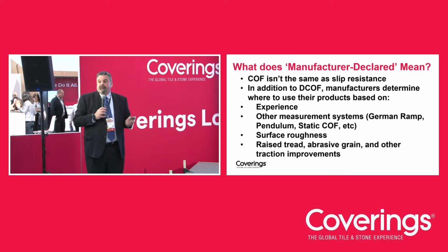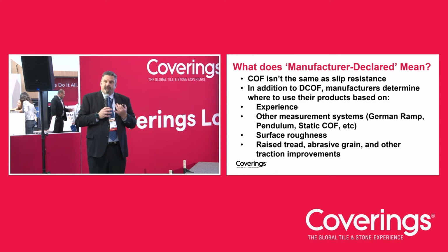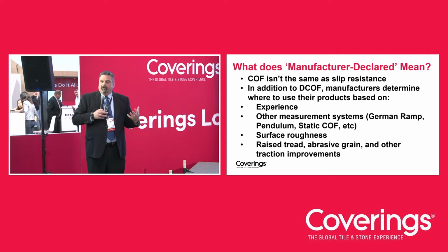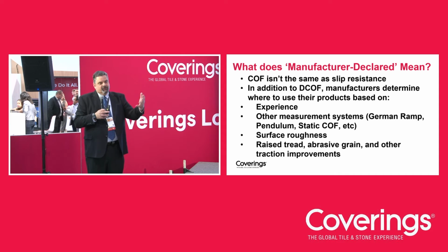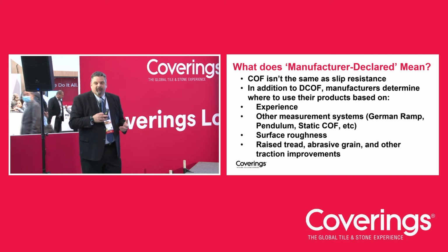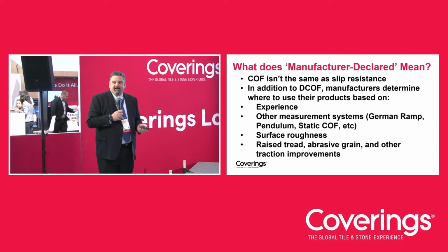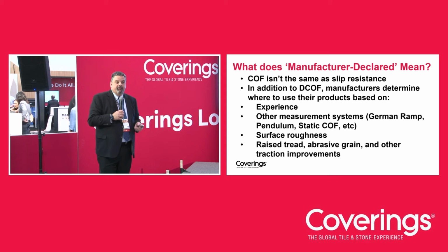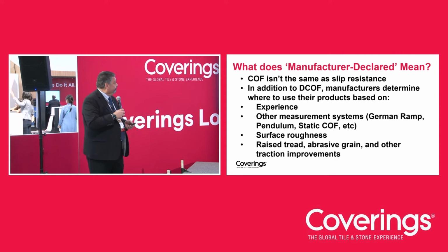There's other measurement systems out there. I've sent some of my products out to have them measured with some of these other systems. There's the German ramp. The German ramp is basically putting a person in standard boots on your tile and then elevating them at an angle until they start to slide. So that's the long and short of it. It's a pretty interesting test. It takes a little bit of effort, but those are some good numbers once you get them.